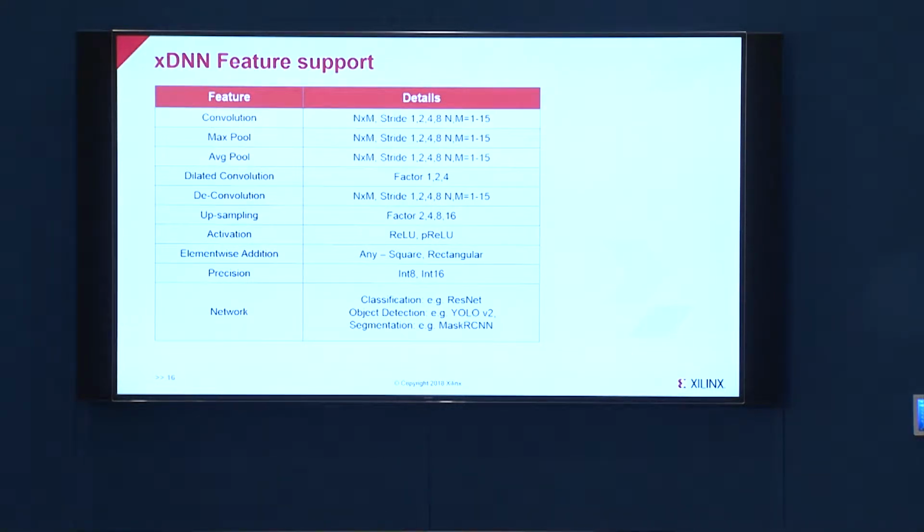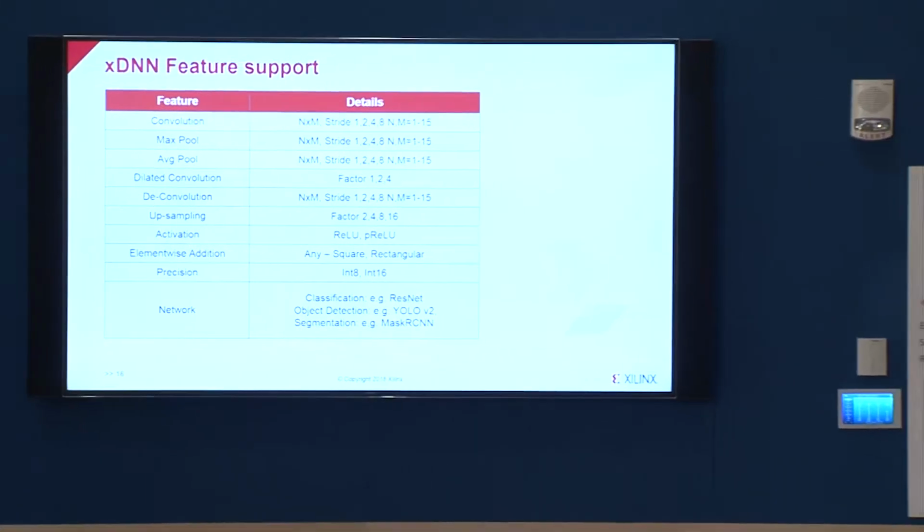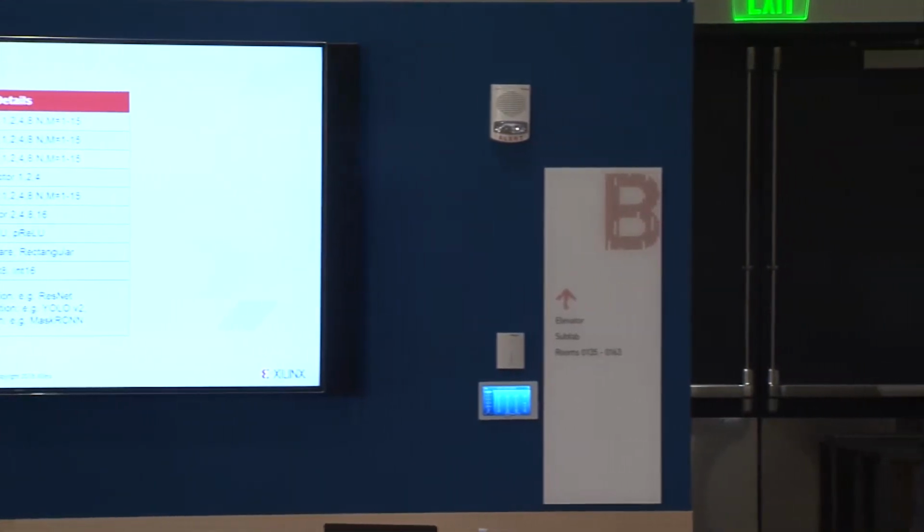So really what we do is we have a compiler, and I'll quickly talk about it a little later. We read the tensor graph, generate these instructions, push it down, this will execute, and that's how a simple CNN overlay, or what they are calling now a domain-specific architecture, works. We looked at how CNN works and implemented something and made it programmable, so that if you don't know how to play with FPGA, you can still get all the advantages of it.